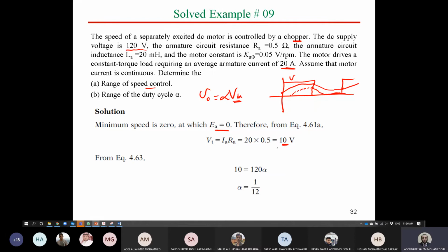Take care, here speed is 0. This doesn't mean no load speed. No load speed means maximum possible speed in the motoring curve at no load current. This is something different. The characteristic we have is like that. This is for DC motor. This is the no load speed. However, 0 speed means here at that point. So this means the characteristic will be like that.